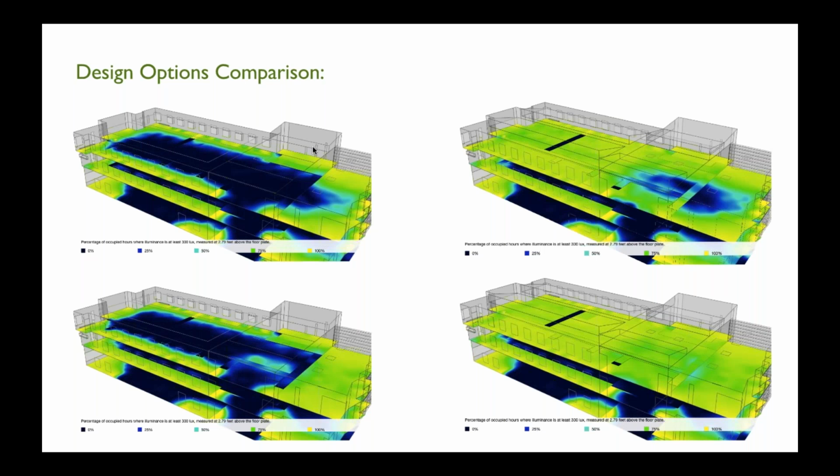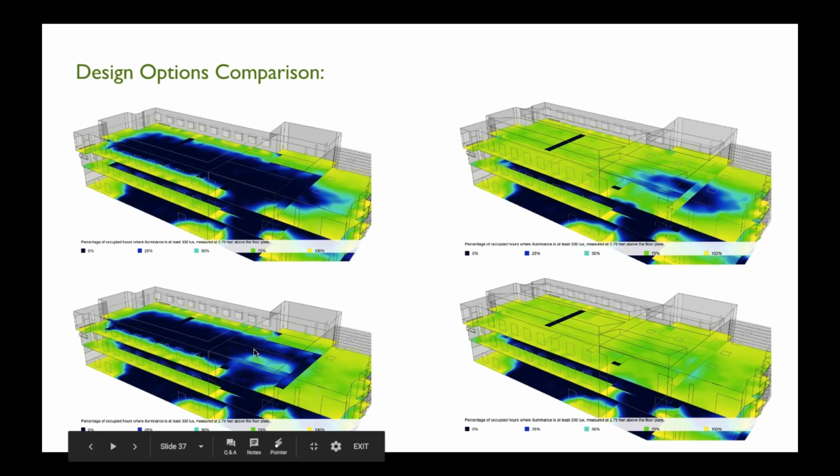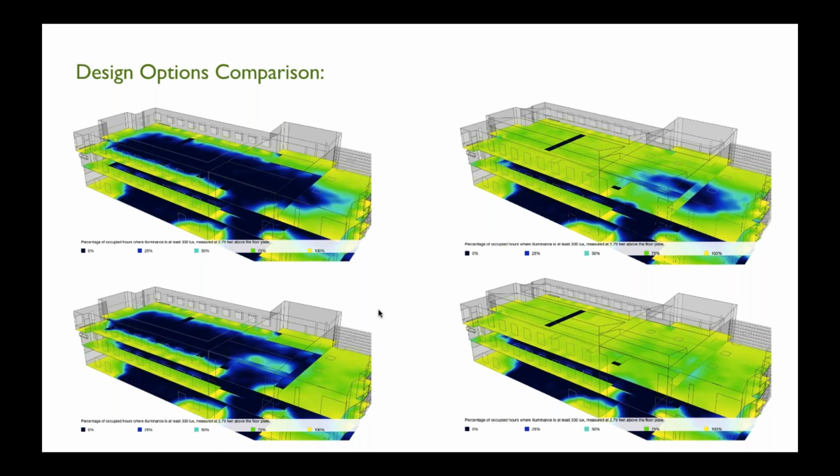That first analysis showed us that we had this fairly dark patch here in the building that needed to be addressed. The skylights have provided some assistance in showing us that we were able to bring some light deep into this space and resolve the light issues here. But of course, those skylights aren't enough to bring full skylight across the floor plate, let alone bring light deeper into the space.